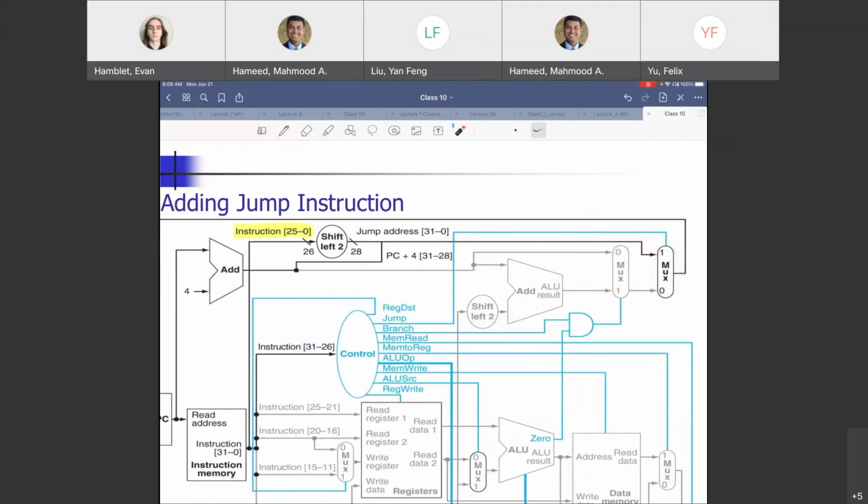So you see there are 2 muxes over there. The first mux over here is selecting between PC plus 4, normal operation, and the branch instruction, right? Branching away from PC to support the branch when equal and branch when not equal instructions.